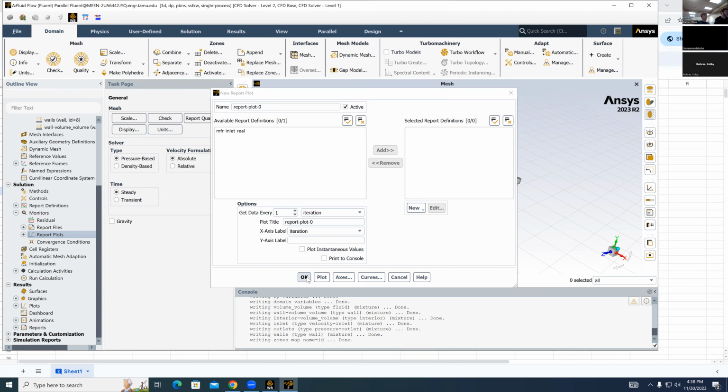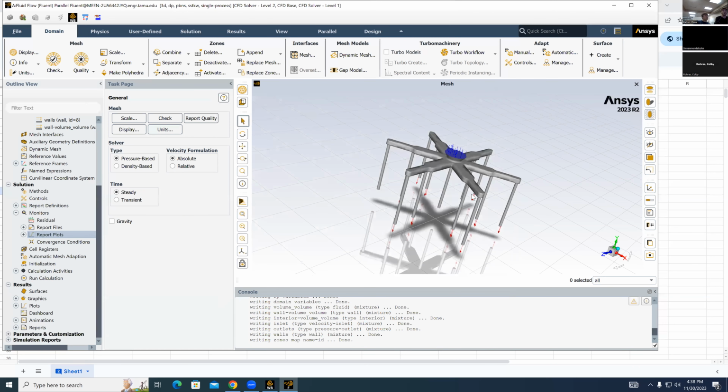I think that's all we're gonna do for now. Or do you want to get something else? Maybe pressure. Pressure should be the same. So yeah, let's just do this for now because the goal of when we ran the simulation to begin with was to get mass flow rate to later calculate the coefficient of discharge, which is a geometric property. So when we do change the mass flow rate or the pressures, that won't matter. It will give us the same number regardless. This is so we can test our real wet fire.